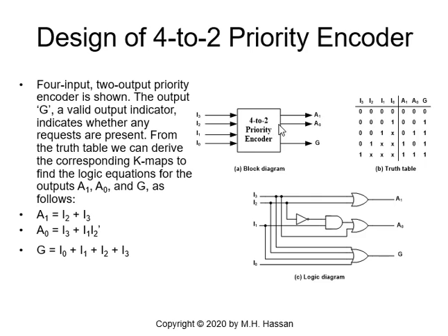The output code which represents the input or device to be recognized is A1 and A0. A1 is the most significant bit and A0 is the least significant bit. If you look at the truth table for the encoder, we will have the inputs I3, I2, I1, and I0, and the outputs, which are A1, A0, and G. G, what's G?